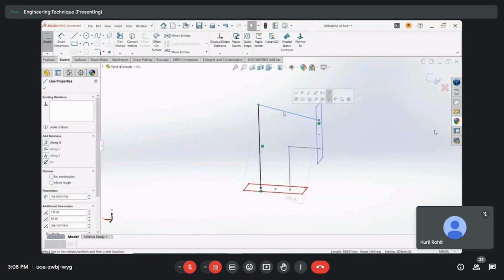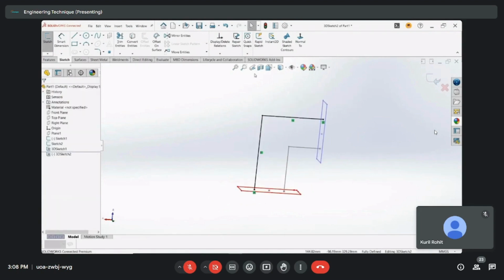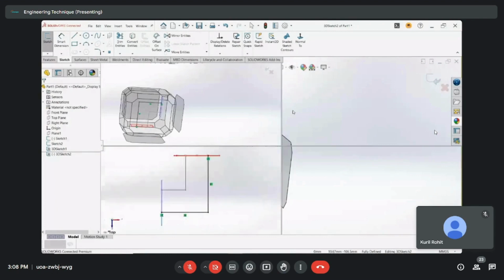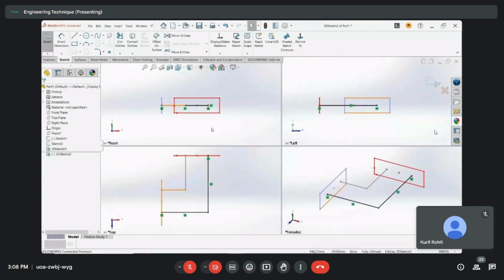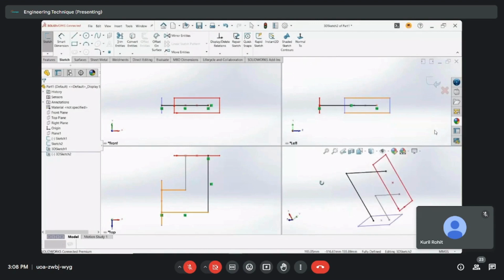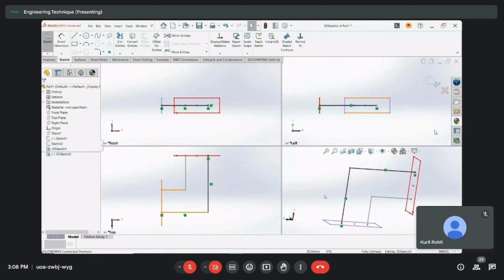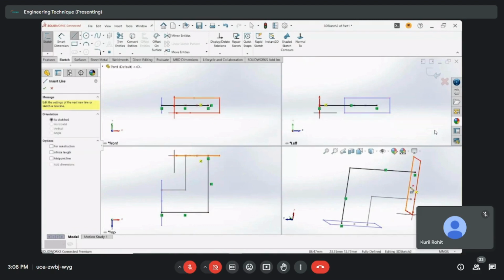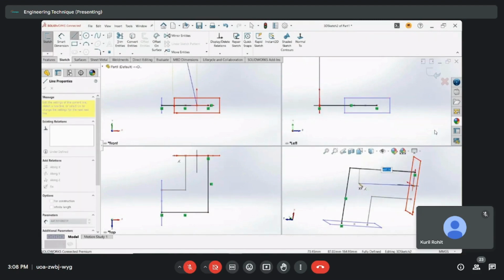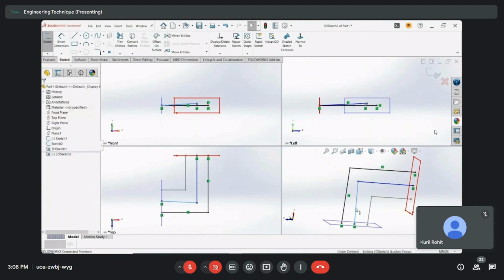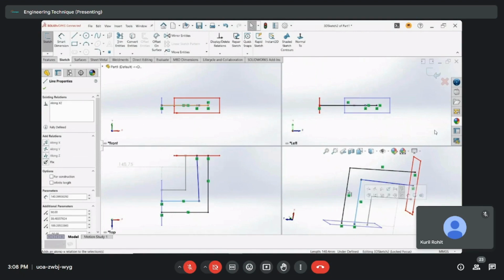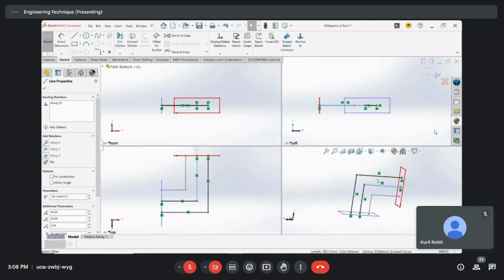As you can see, there are many degrees of freedom available. All 12 degrees of freedom are available in the 3D sketch environment. So it's easy to draw a 3D sketch, but you have to know in what plane you are working. You can also utilize this kind of view to create your 3D sketch. That will help you a lot while moving forward in routing. It will provide you a view of all planes that you are going to utilize. So this is how you can utilize 3D sketch to create your route. It's just a demonstration of how to create a 3D sketch mainly.